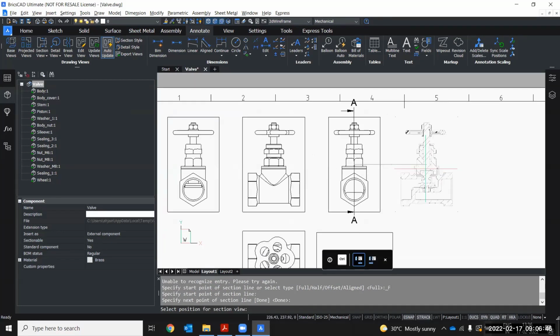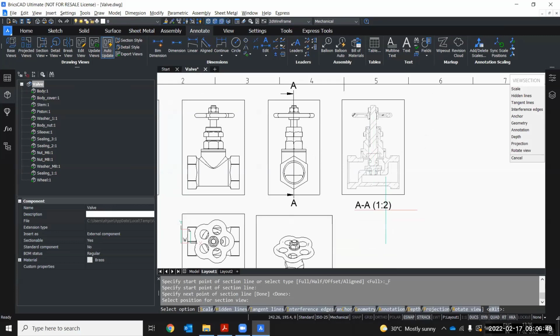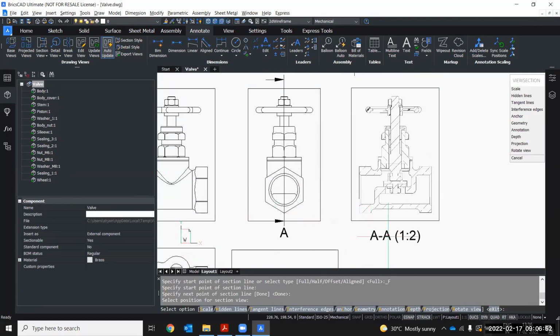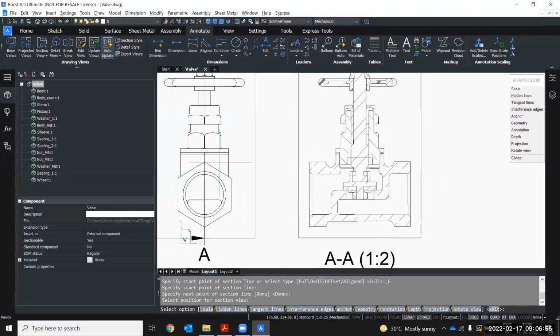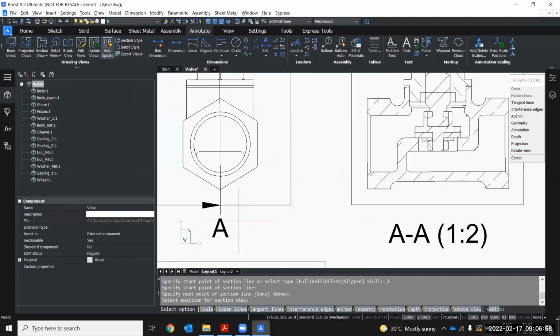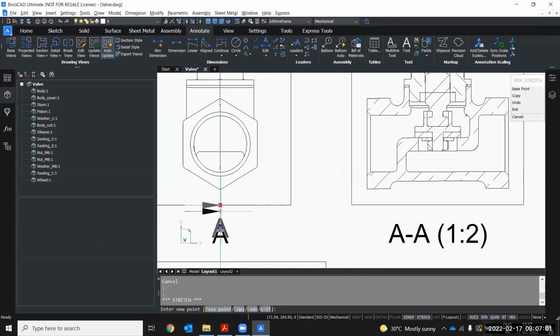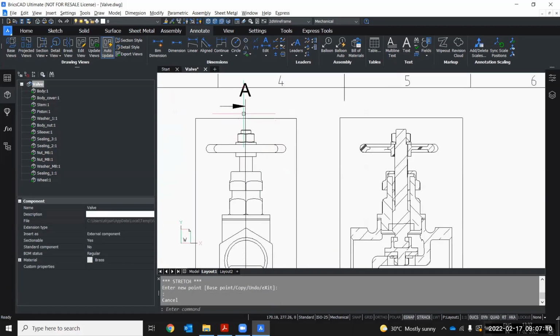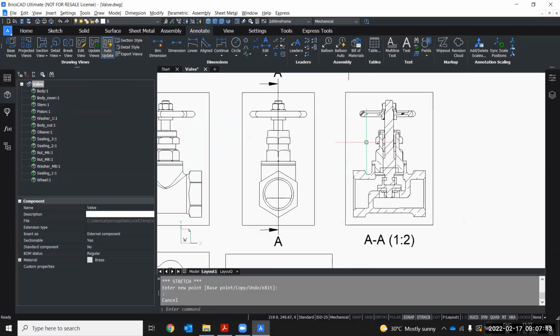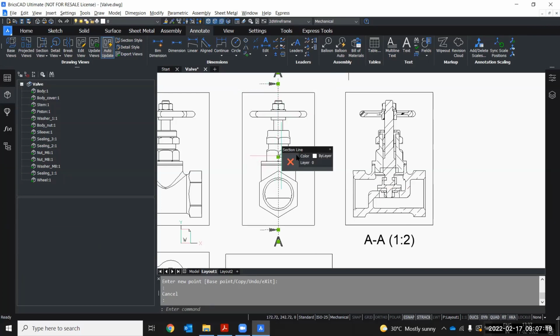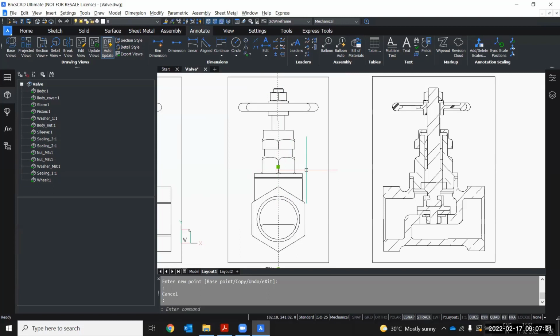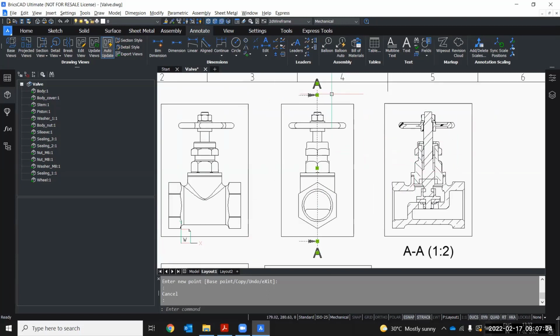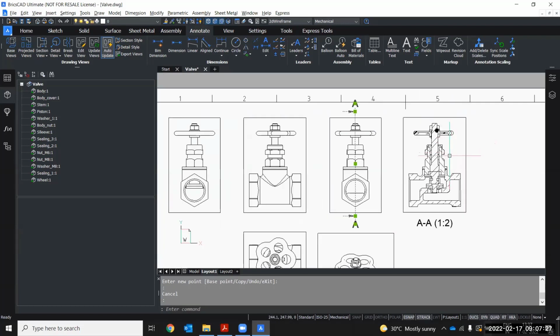Okay, so just place it right across by its side, and you get, along with the annotations and the sections, the view of the section that we just cut. Okay. So you can just click over here. You can bring this arrow downwards as well. So in case you move this particular section line, it will again rebuild the section view for you. So in case you're doing any changes for this particular section view, let's say you drag it from this particular point a bit to the right, the views would update. So any changes to the section line, the views would update automatically.